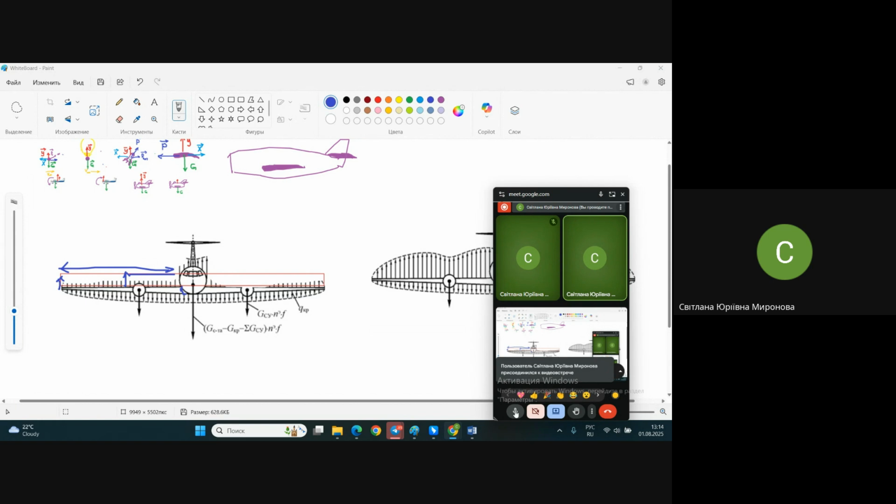Great. Sorry. And bending moment. So bending moment grows closer to the fixing, where the arm is larger. Here it's practically no bending moment, because the arm is little. But when it will be somewhere here at this place, it will be already a significant load.